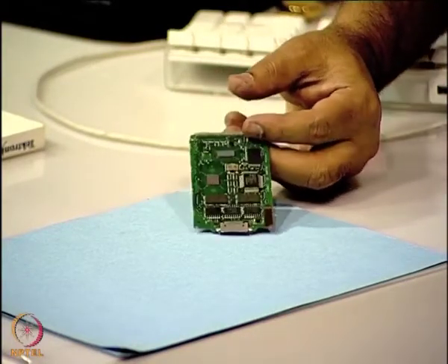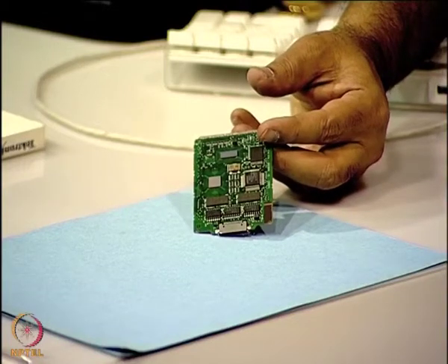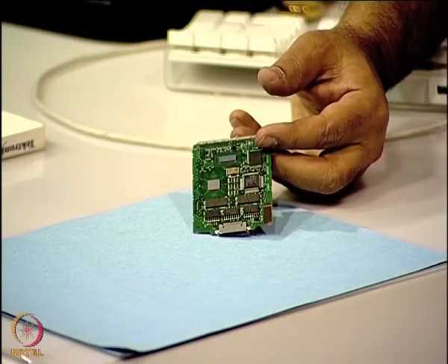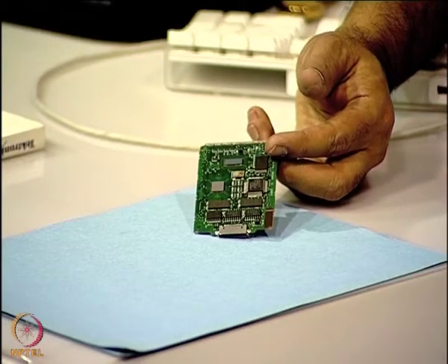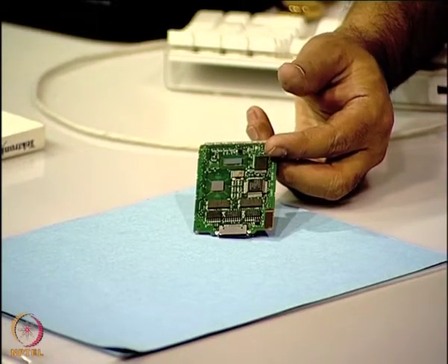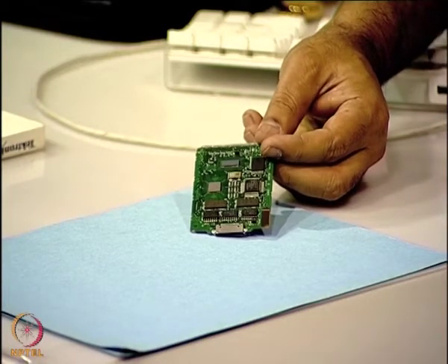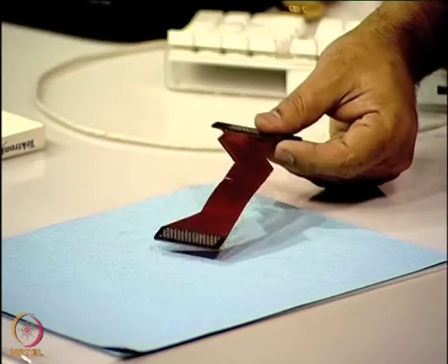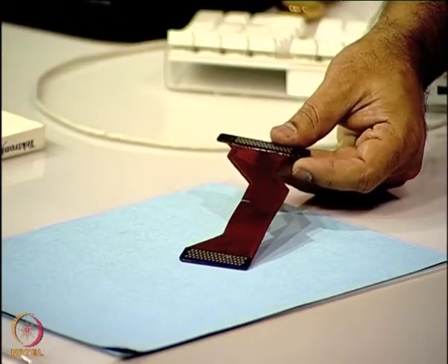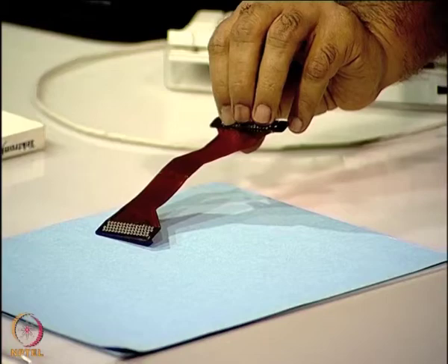And here obviously, from this vision you cannot look at the cross section, but I can tell you that this contains micro vias of the order of 90 microns. And you can also make boards like a flex circuit. You can see here, this is a rigid flex board, and you can also make a completely flex board. Now, I have been taking you through the various process steps in the manufacture of printed wiring boards.